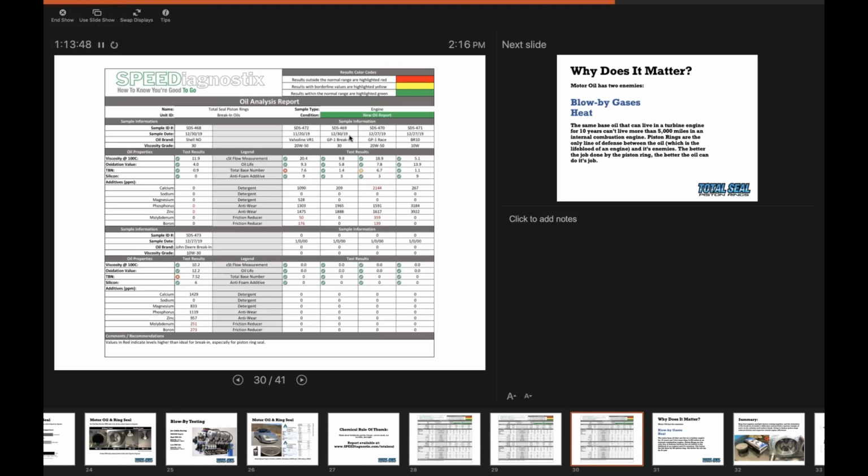So I understand the benefit of thin rings. A lot of companies are thinning the oil ring as well as second rings. How are you controlling crankcase pressures and oil control in higher horsepower wet sump street engines? Not LS engines, that's a different issue. Well, oil ring tension does matter, obviously.